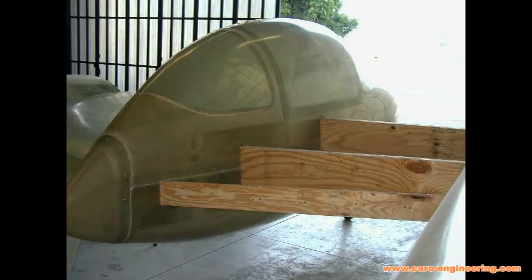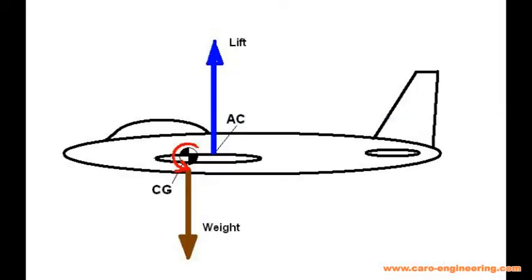So far we talked about the wing and fuselage separately, but of course they will need to be joined together. The positioning of the wing on the fuselage relative to other parts of the airplane is obviously very important. As I have already hinted at, the position of the aerodynamic center of the airplane is mainly determined by the wing. The aerodynamic center of the whole airplane is that one point where we imagine all the aerodynamic forces created by the airflow are combined into one vector.